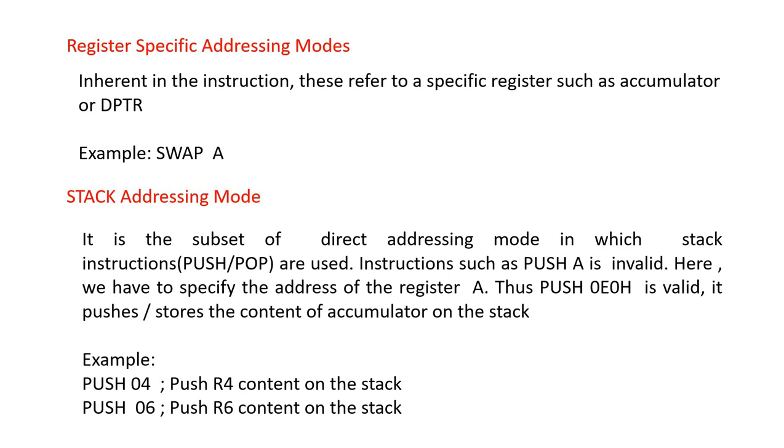Then another is the stack addressing mode. It is a subset of direct addressing mode where the address is directly specified, but it uses the operation of the stack with the help of the instructions PUSH and POP for entering as well as retrieving data to and fro from the stack. PUSH 04: the content of R4 is pushed onto the stack. The content of R6 is moved to the stack when we use the instruction PUSH 06H. So these are all the varieties of the addressing